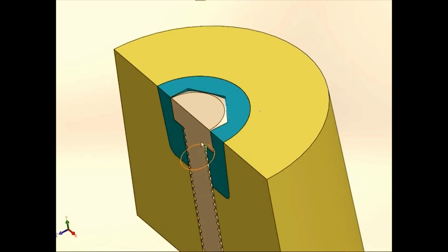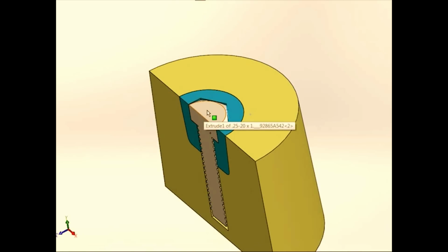They also recommend that you put a clear acrylic spray on some of the metals. It helps the hot molten material adhere to the metal. Sometimes with shiny metals, the plastic material being extruded has a hard time sticking to it. So if you just use like a clear Krylon acrylic spray, it gives it just that little bit of extra stickiness to start adhering to the metal.